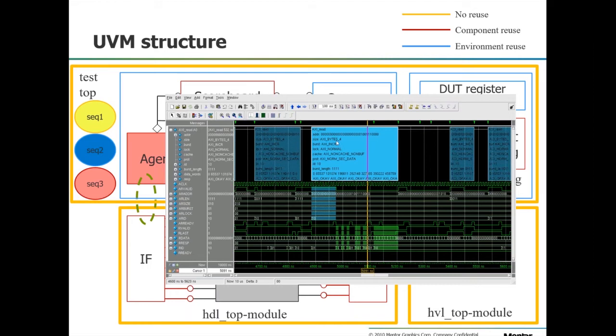So this was an AXI read with all of these different parameters. If you want to, you can go down to the signaling level down here and look at what was happening at the signaling level, but it's a lot easier to debug at the transaction level when you're working at that level. So that's another thing that UVM does, is it raises that level of abstraction up.